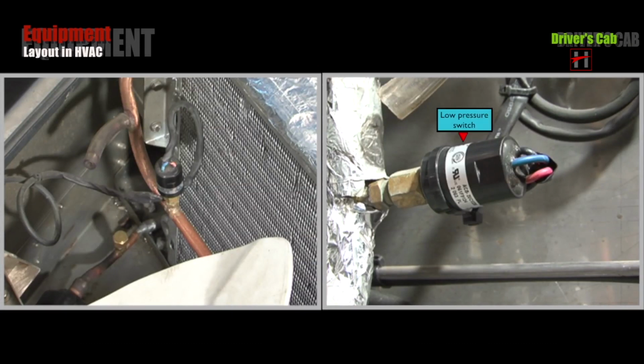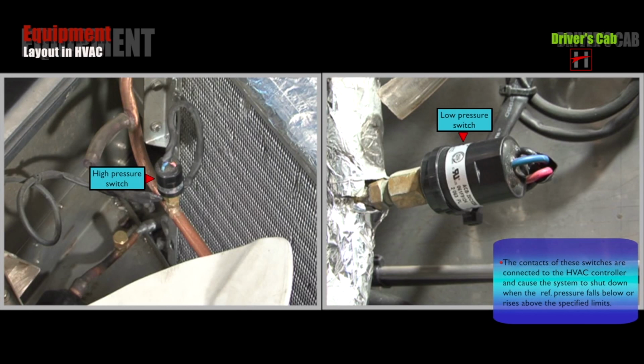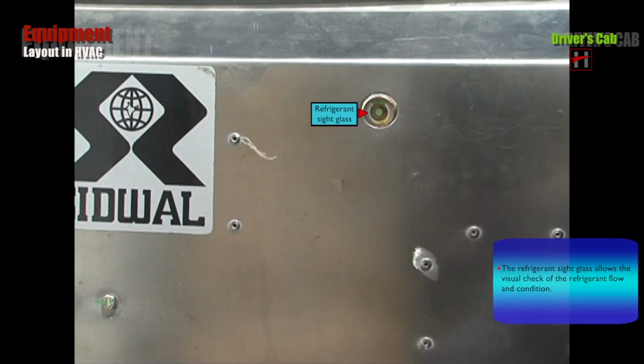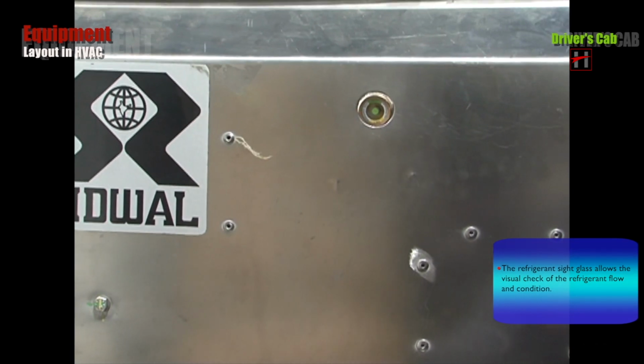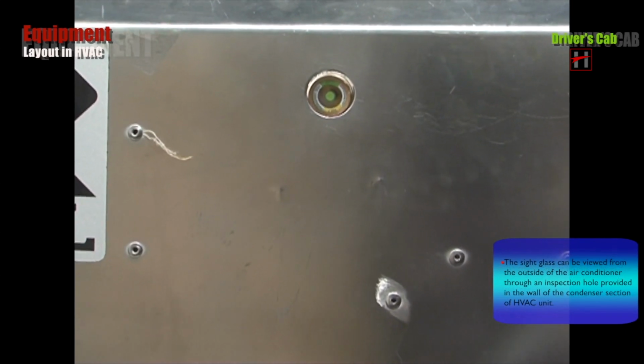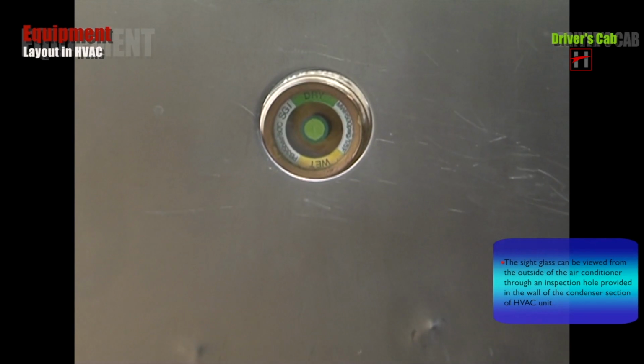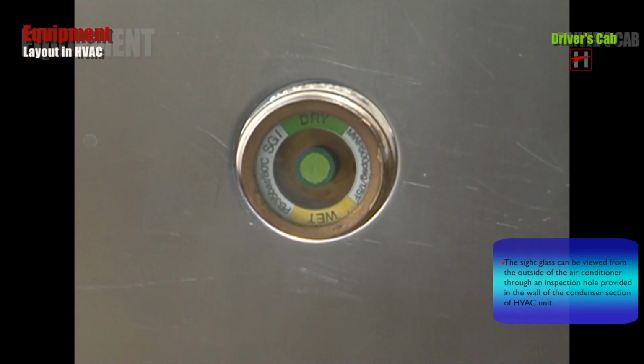These are the low and high pressure switches. The contacts of these switches are connected to the HVAC controller and cause the system to shut down when the reference pressure falls below or rises above the specified limits. The refrigerant sight glass allows a visual check of the refrigerant flow and condition. The sight glass can be viewed from the outside of the air conditioner through an inspection hole provided in the wall of the condenser section of the HVAC unit.